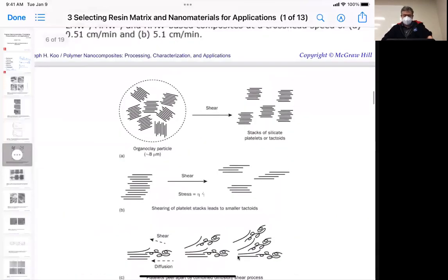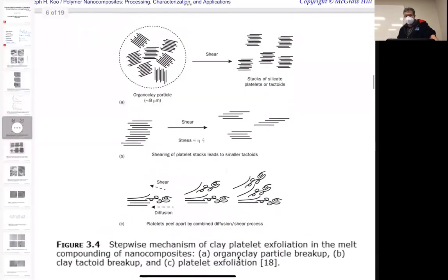Okay, and we've already seen this, that one of the reasons platiness is really important in having that shear is we go from the big macroscopic particle to breaking it down into tactoids where all of the plates are aligned the same direction, but there's still that interfacial interaction between them. We have to shear them apart, but then immediately, if they get next to another particle, another surface, they're going to reorder.